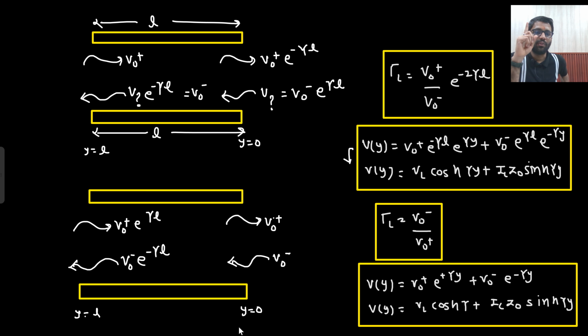That concept is the lossy Smith chart. The Smith chart will be the same for lossy and lossless line, because in the Smith chart what we plot is ZL dash. So ZL dash will not depend on your transmission line. ZL dash will be supplied by the user. But in the VSWR circle, what do we do? We walk along the transmission line. Once we walk along the transmission line, then our VSWR circle will change.